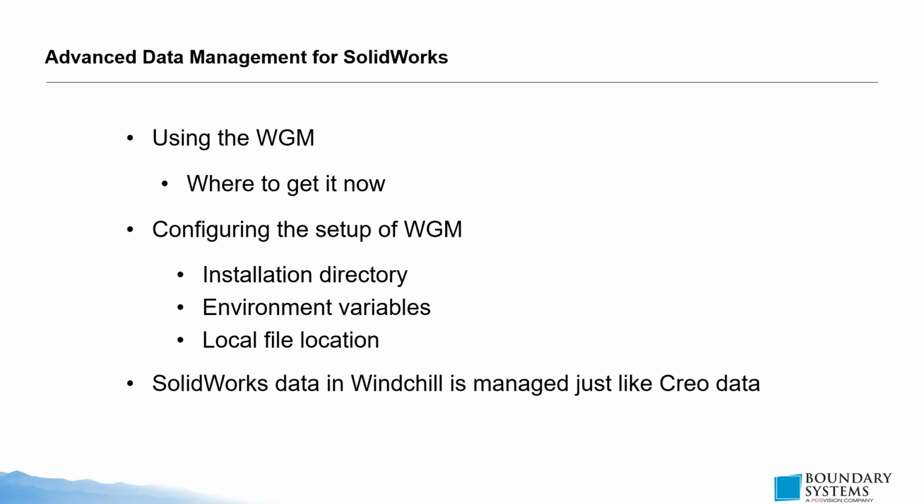With Windchill and SolidWorks, the Workgroup Manager is what is used to communicate directly from SolidWorks into Windchill and vice versa. Previous versions of Windchill used the software downloads area to download the Workgroup Manager. The requirement was that the Workgroup Manager and your version of Windchill had to be on the same build code.